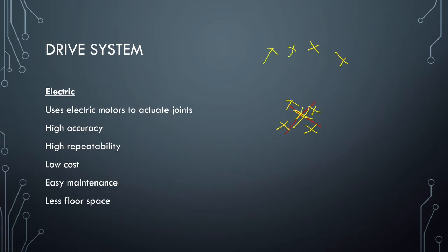So when we talk about repeatability, repeatability is the ability to be consistent. So a robot may be repeatable. It might consistently hit the same spot over and over and over. So this might not be very accurate, but we do know that the robot will always be in this spot. So that kind of helps. Sometimes we can adjust things around that. Ideally, you do want high accuracy and high repeatability for a lot of applications, but just to differentiate the two.